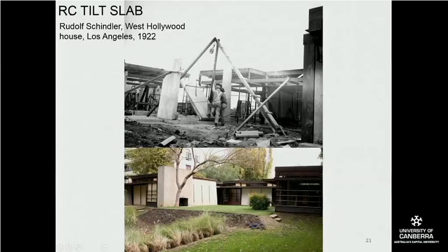So with the lower rise examples that you might see in your travels around town, up to two, three, maybe even four stories, but I think about three stories is the maximum, you can get buildings that are made completely with precast concrete panels without any other kinds of structure. So this kind of technology has developed past the frame. But if you have taller buildings, then you need a frame to hold on to it.